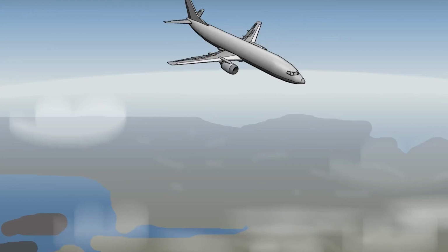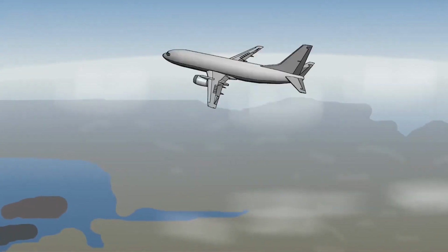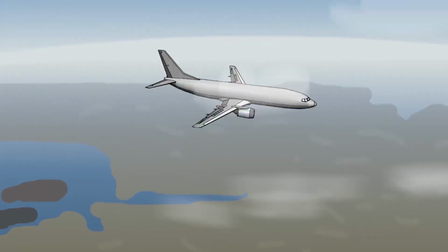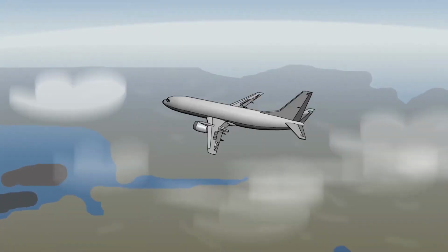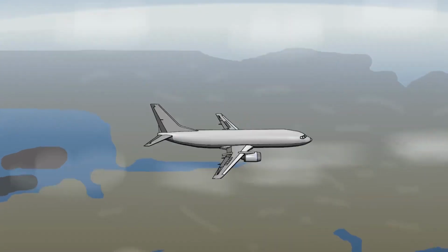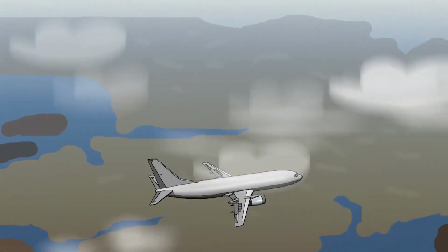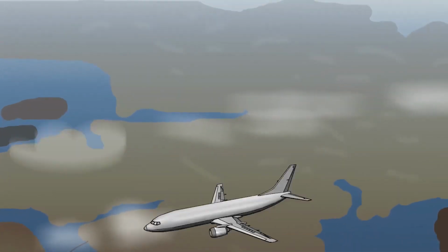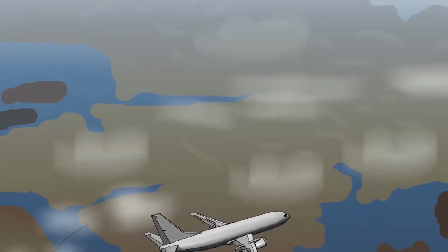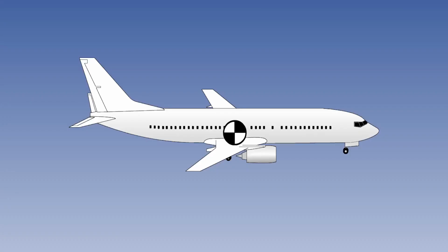Both the total mass of an aeroplane and the distribution of that mass will influence spin characteristics. Greater mass generally means slower initial spin rates, but these may increase if the spin is allowed to progress. The higher angular momentum will extend the time and height necessary for recovery in a heavy or heavily loaded aeroplane. Within the loading of the aircraft, the centre of gravity is more significant than the mass itself, as it affects the aircraft's resistance to spinning, as well as its behaviour in the spin.